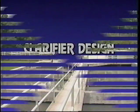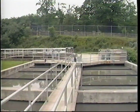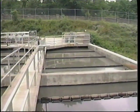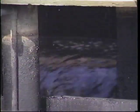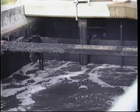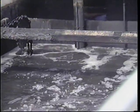Now let's take a closer look at clarifier design. A rectangular clarifier is usually used as a primary clarifier. If there are multiple clarifiers, the influent should be distributed evenly to the clarifiers. When the flow enters the clarifier, it first runs into a baffle. The purpose of the baffle is to slow the velocity of the wastewater and to distribute the wastewater evenly through the clarifier. Without the baffle, short-circuiting would occur.